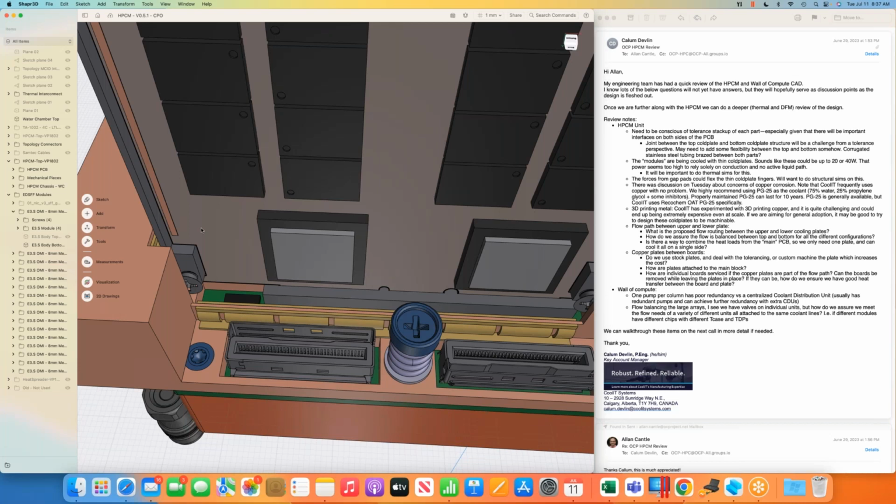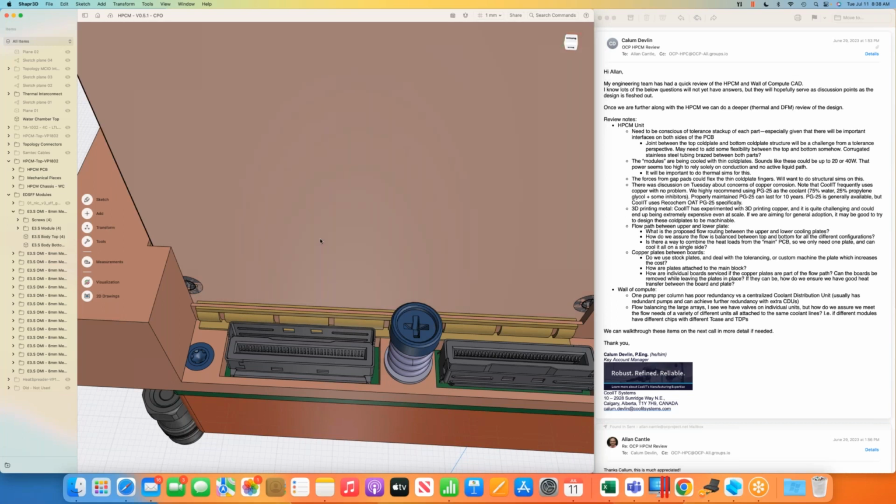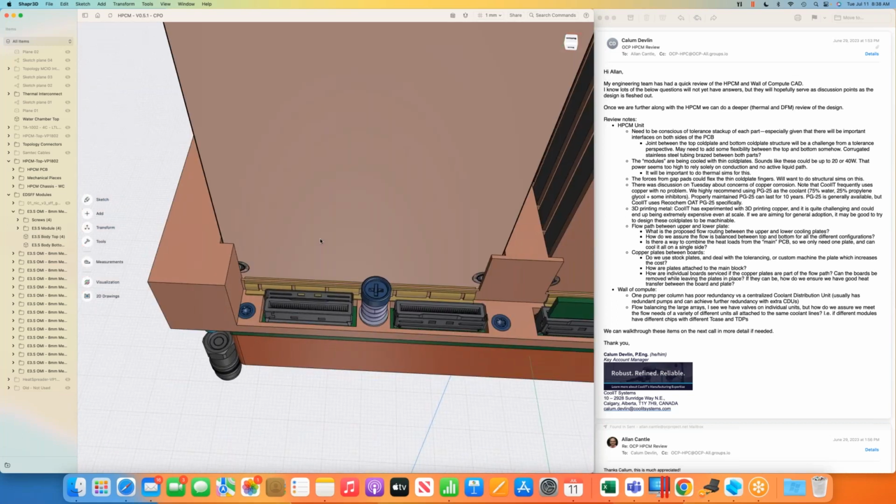So we would replace that with a copper lid, or maybe we can get away with aluminum, depending on the conductive requirements. And we just put that lid. So minimal modifications for the SSD and memory manufacturers is the idea. Or we could even modify them ourselves in an experimental sense. Okay. So that definitely helps, because my tolerance concern was about between that cold plate and the card itself. But if it's being mounted together, then you're good in that sense.